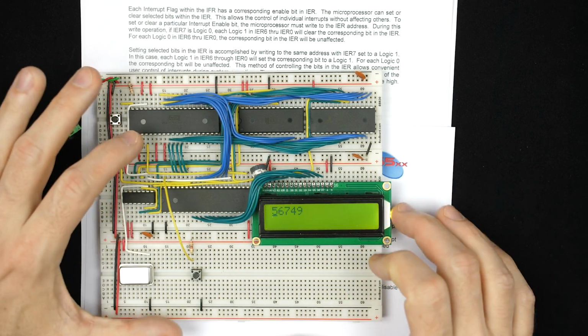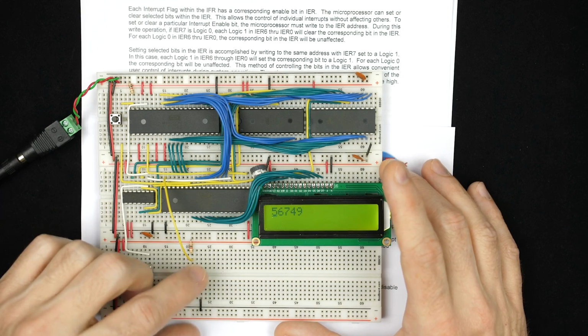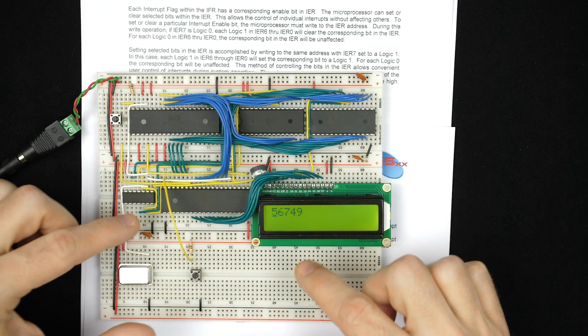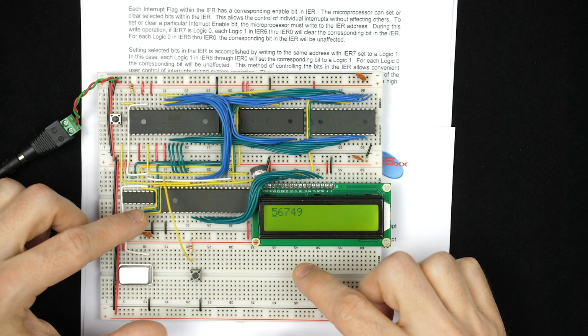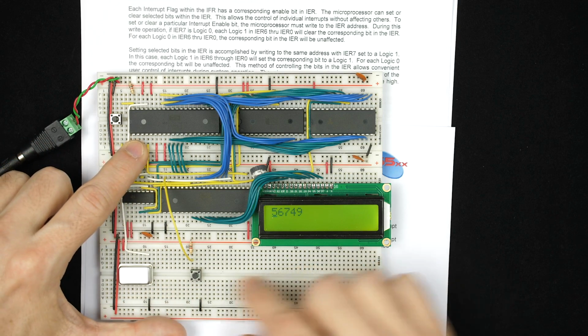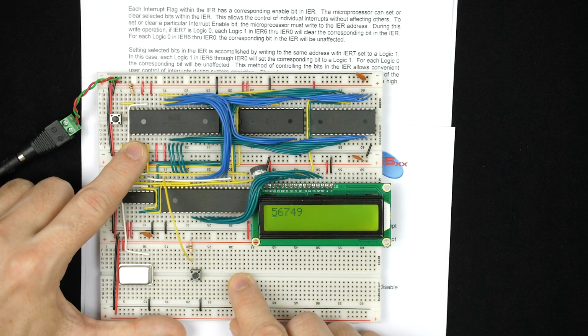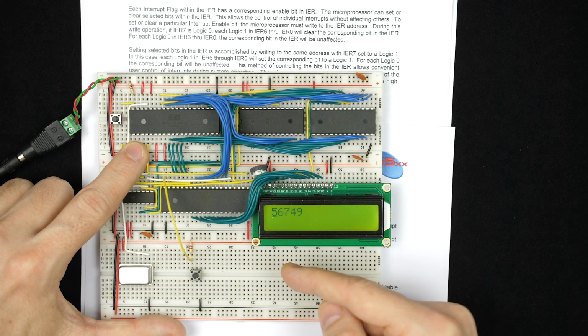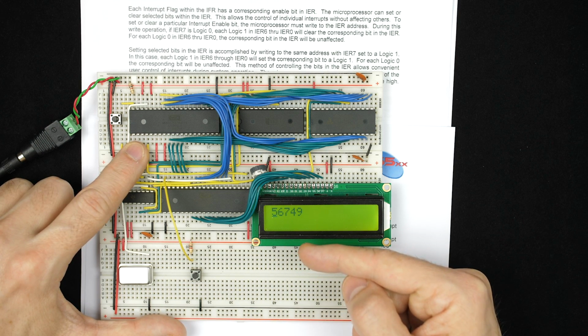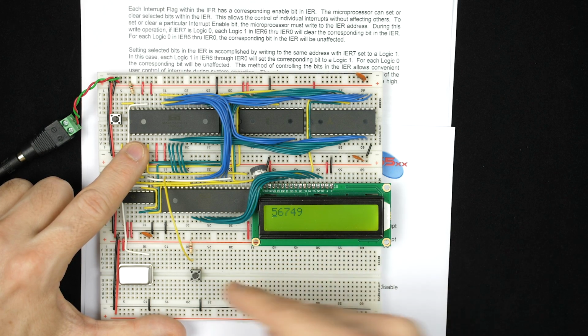But now what we need to do is the thing that we couldn't do before, which is clear the interrupt. So before, the problem was, when I push this button, the interrupt line would go low because it was directly connected to it. But then that interrupt would keep firing because as soon as the interrupt incremented the counter, it would return from the interrupt routine and then say, oh, wait, there's still an interrupt because the button is still pushed.